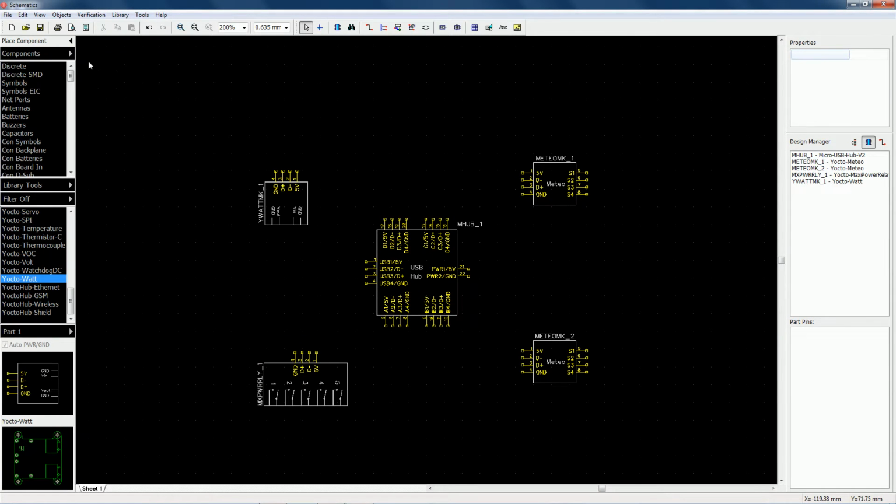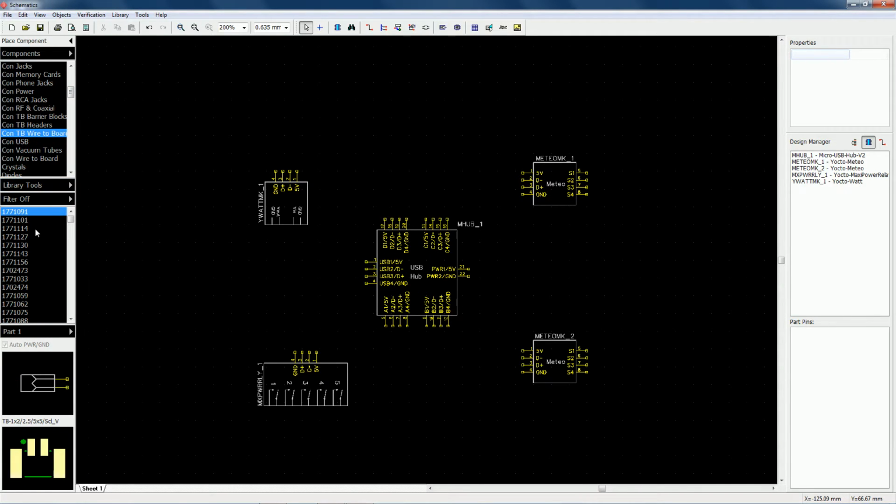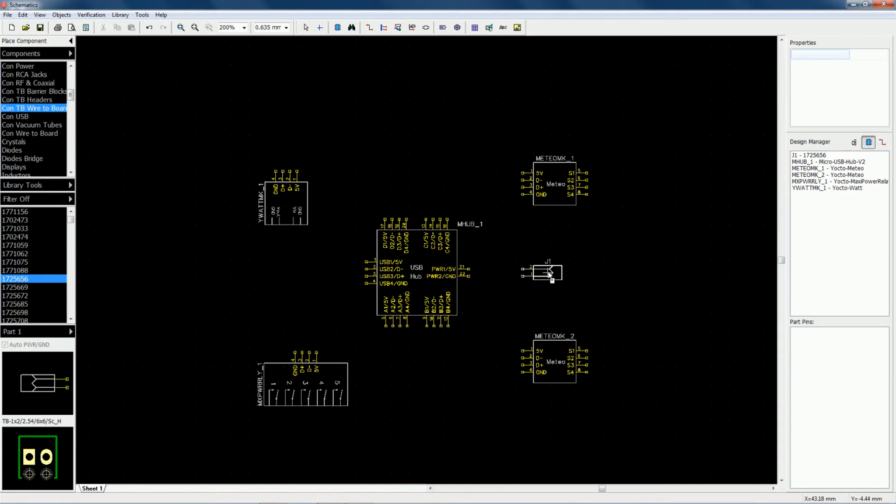If you need standard connectors, wired to board, things like that, you'll find plenty of them in the DipTrace library. Often they are numbered with the manufacturer part numbers, so you have to browse a little bit through them to find the right one. Now we can start connecting the devices together. So remember, here we are just in a schema for now, so these are just logical wires to connect stuff together. Don't worry if the connections don't look nice immediately, it's very easy to fix them afterwards.